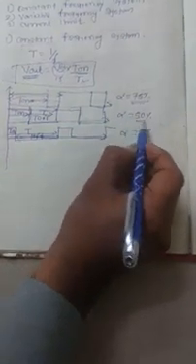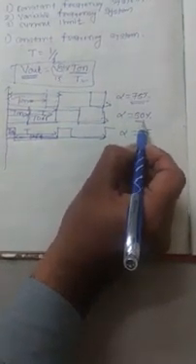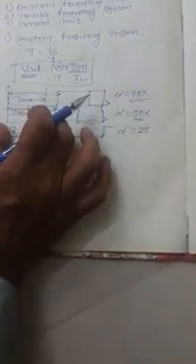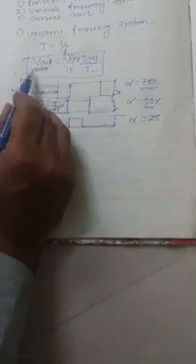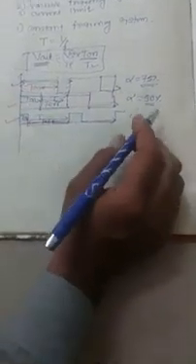Similarly, with a 50% duty cycle, T on time is 50%. In the figure, in case 1, case 2, and case 3, the total time is constant, but due to the change of T on time, 75%, 50%, 25%, the output voltage is controlled in a buck converter.